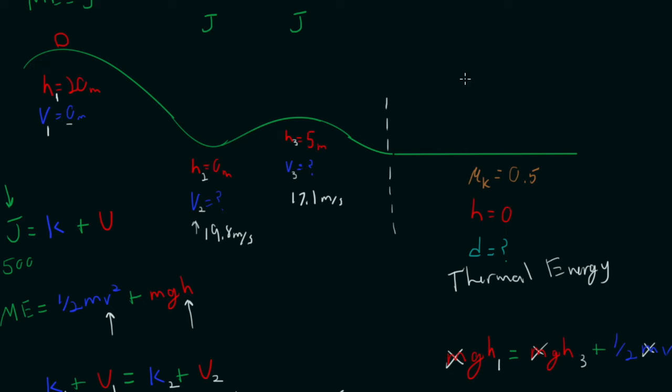But what's really happening here is we're having the work of friction. So we have work being done by the force of friction times a distance. Well, how do we calculate friction? Well, that's going to be Fn times mu k, which is then still times d. Well, what's Fn going to be? Well, Fn is just going to be the opposite of our force of gravity. And since these are all scalars, we don't need to worry about positives and negatives.